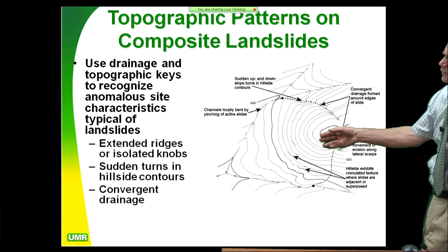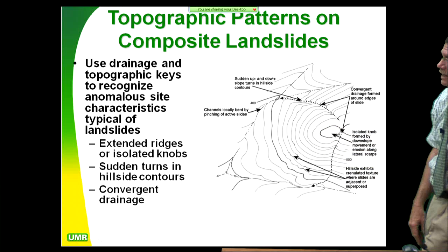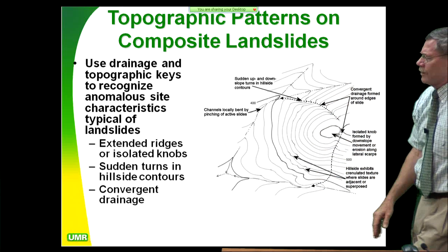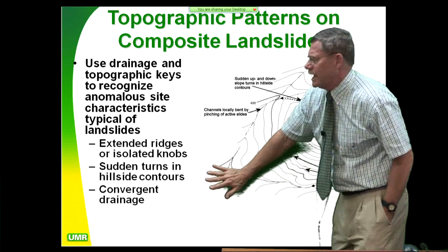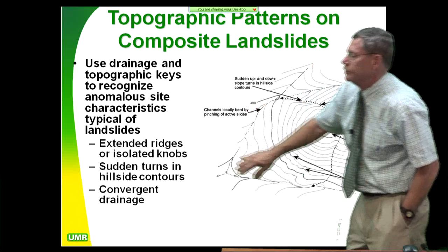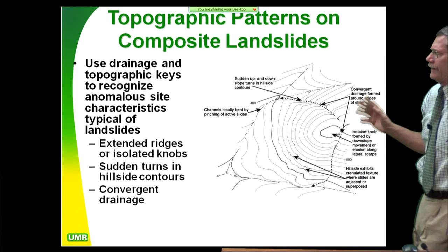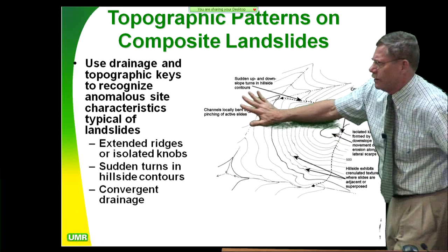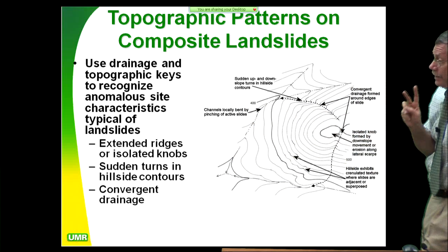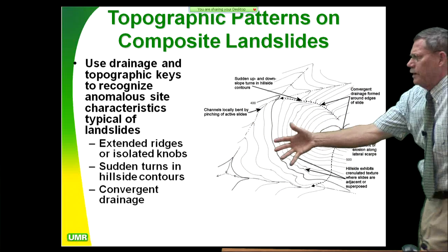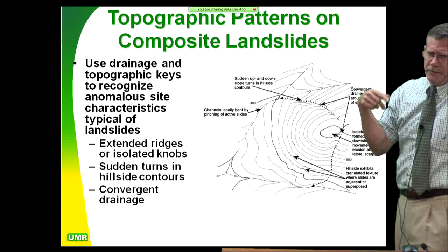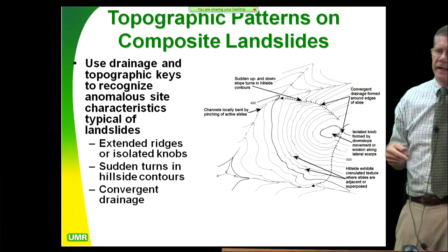Now, there's a bunch of these with Three Gorges Dam. They have a lot of these kinds of features in China, and they're not too concerned about them because they're going to have water out here, and the water is going to buttress the slope, and that's true, and that's fine as long as that water doesn't suddenly drop for some unforeseen reason. If that ever happens, then you're going to see a whole bunch of these things move. That's what happened to us in Lake Roosevelt behind Grand Coulee Dam back in the 1950s.